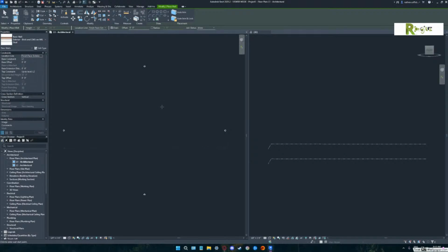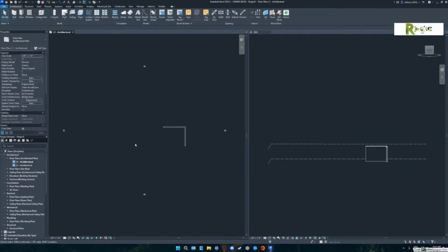Does it matter where I start, or can I just start anywhere? Like I said, you're going to want the basic building to be centered up in those 4 white elevation marks, and that'll be more clear in a minute when we start showing you how they work. Notice how it's giving you a number. You see that number? Type in 112 right now. Don't do anything. Just start typing. Head that direction. Just keep it level. Don't move your cursor. See, when you move your cursor at an angle, then it's going to